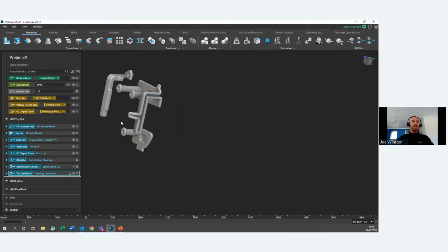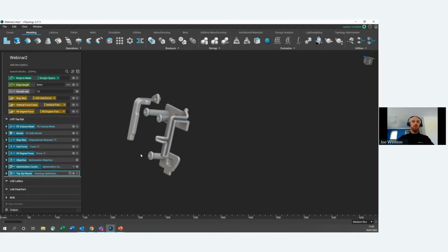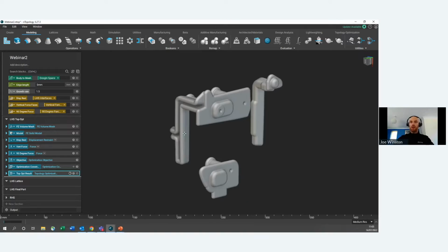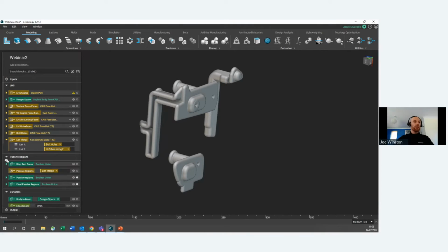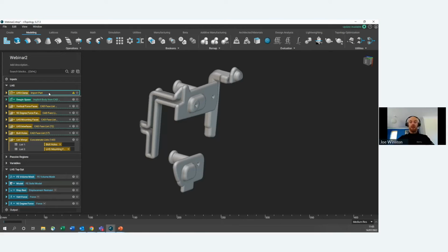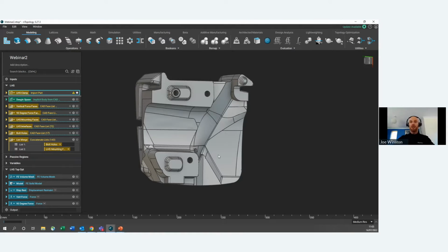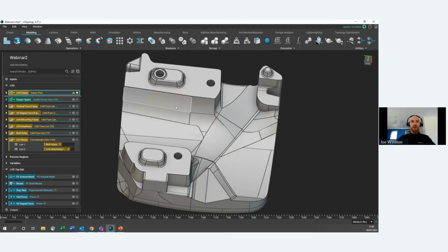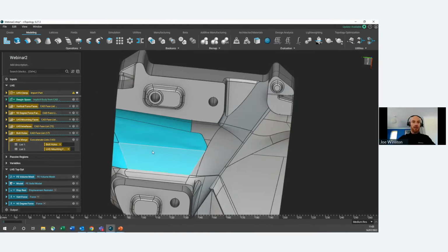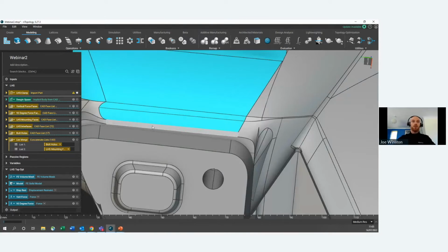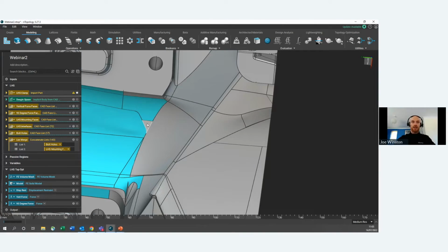It's a fairly computationally heavy task to do a topology optimization, but in nTopology, because it's doing it all through maths and algorithms, we're able to do multiple things at the same time. So while the topology optimization is running, we are going to jump ahead and start creating a lattice on this face here. So the first thing I'll need to do is just select some CAD faces I want to turn into lattice structures. All I'm doing is holding down Control and left clicking to select all of the faces that I want to turn into a lattice.